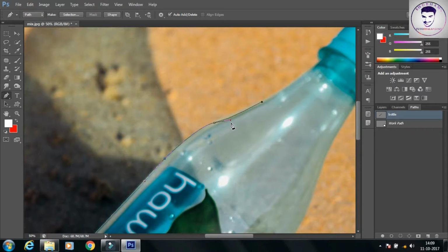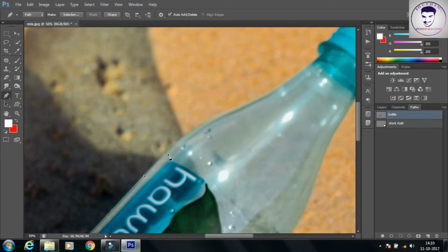If you create a curve by using the anchor points, then it will automatically create a curve again in the next step instead of creating a straight line. And in the third step, it will again create a straight line. So if we want to remove this problem, just do one thing. Just delete the handles. You can delete the handles by holding the Alt key and pressing over the anchor point. Here you can see the sign is changed. In the pen tool, always remember one thing. When you create a new anchor point, just delete the handles by holding the Alt key and clicking on the anchor point.